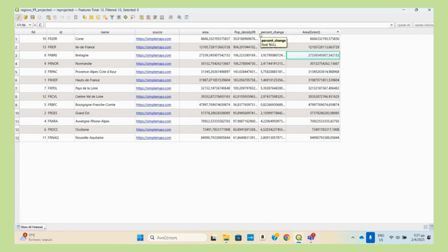And now, just to add here, that if we are working with geographic coordinate systems and we are trying to calculate the area, our calculation will be in degrees and we will see some weird results that we don't want. That's why we are projecting all data. It's boring, we know, but it's so useful and so significant, and people do not realize it because they now have the possibility to download everything from the web, and they don't understand that. Exactly. Okay, let me move on.